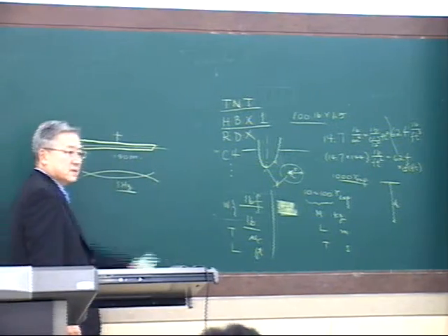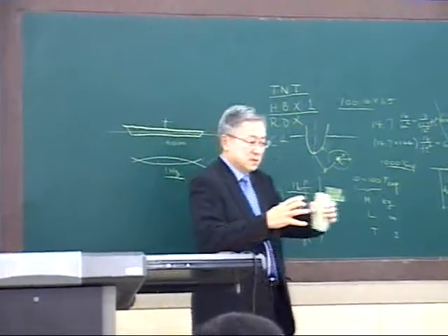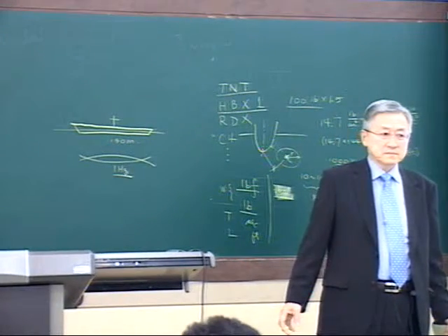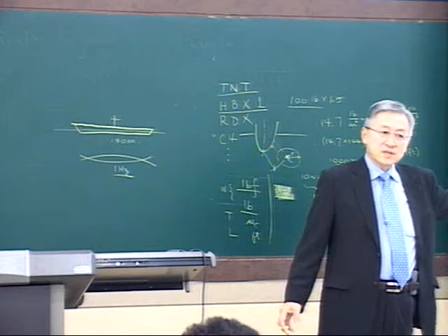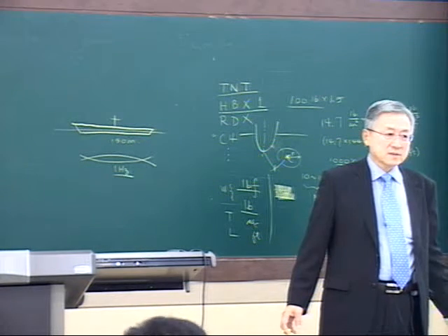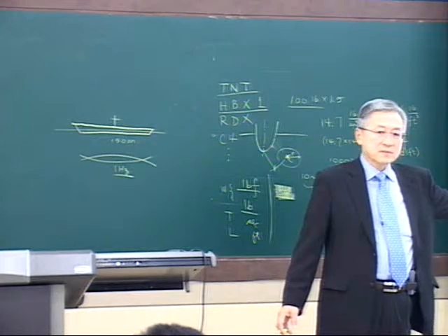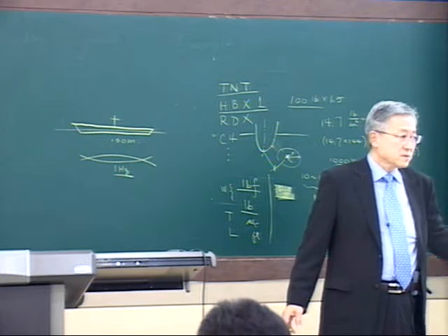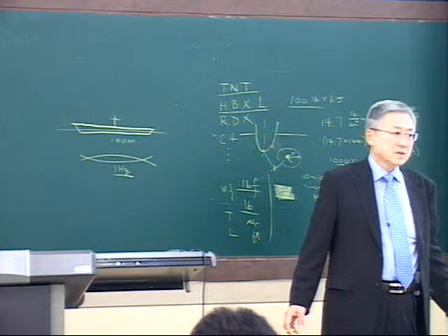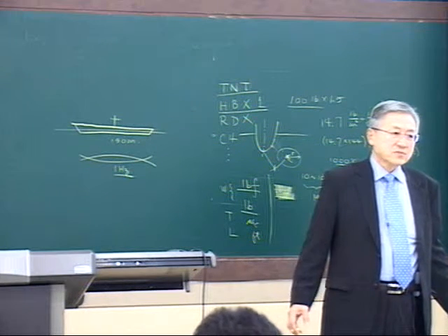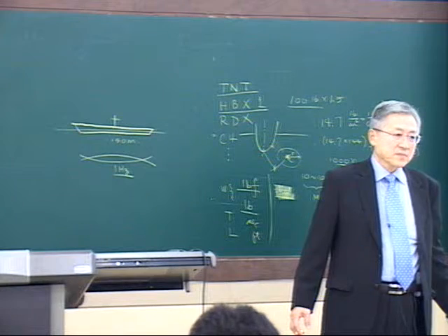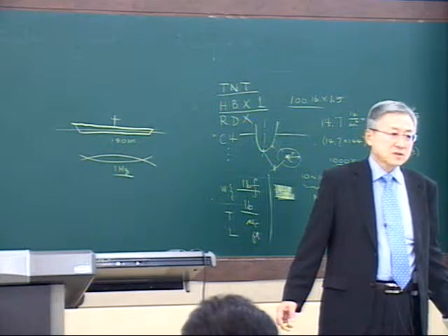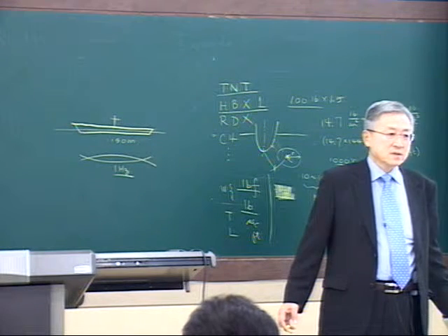This gas bubble oscillates at very low frequency. Could it be 1 second? Less than 1 second. Let's say 1 second. Then what's the gas bubble frequency? 1 hertz. 1 over T. So excitation frequency is 1 hertz. And the ship natural bending mode frequency is 1 hertz. Then what happened?